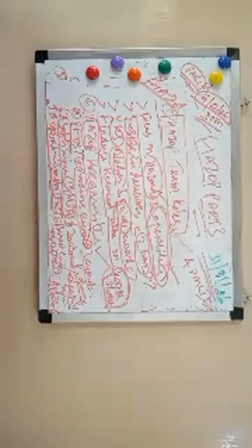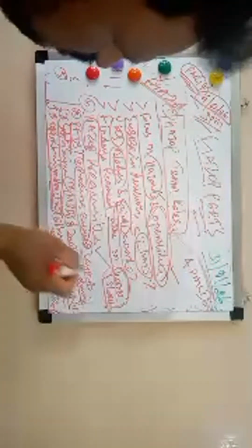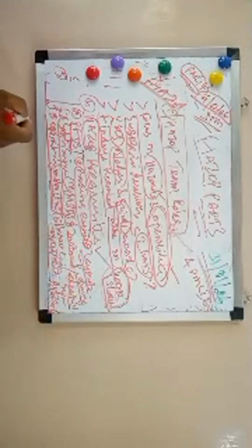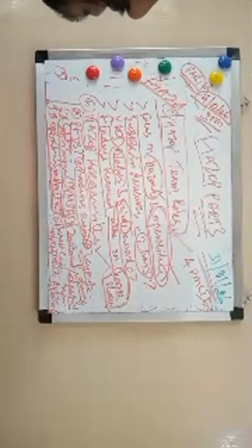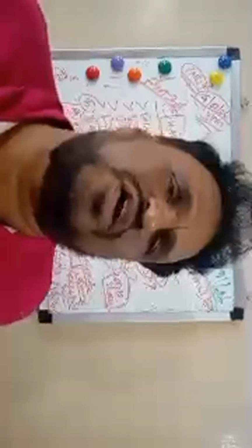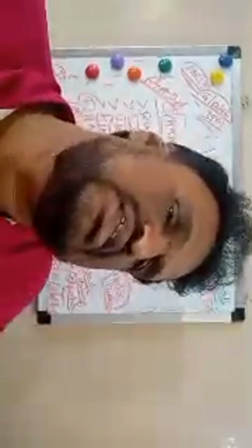During that study, you have to provide the PFDs, the layout drawings, the MSDS and the operating instructions, and the instrumentation and electrical engineer must be there, and the safety engineer must be there for knowing the hazards. So these are the two things for part 3.